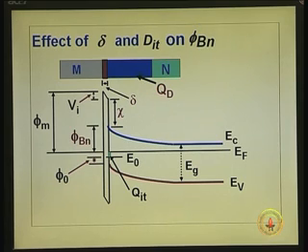This is the new diagram, a fresh appearance for this metal semiconductor contact. This was the situation in the first lecture on metal semiconductor contacts. We saw that as we keep on reducing the thickness of the delta, ultimately we saw this or this. So, we have put back the delta there. Metal, that thin delta layer of insulator which is always present, you can't make it 0. This is the depletion layer, QD, charge in the depletion layer plus, and this is the neutral region.